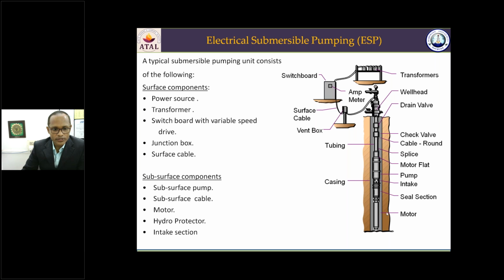Now when the motor rotates, the oil expands because of the heat generated. So this oil goes into the seal section. The seal section, as I told you, acts as a reservoir. And when the motor requires to be cooled, this seal section provides the extra oil for cooling the motor when it is stopped. So this seal section is a very important part of this subsurface component.